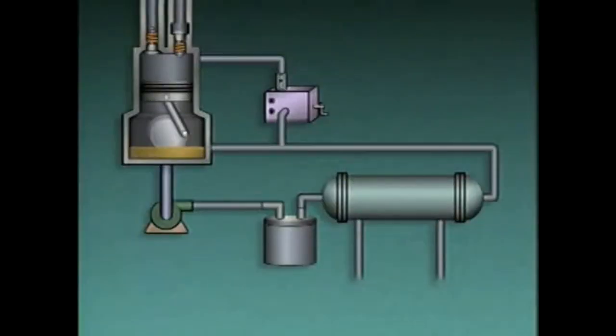Compressed gas systems use auxiliary devices to remove oil or moisture from compressed gas and to prevent overpressurization. Two devices that are used to remove liquids from compressed gas are oil separators and demisters. Most reciprocating compressors that contain pistons use oil to lubricate the piston rings. During compression, some of the oil can become mixed in with the gas. This oil must be removed from the gas to prevent system equipment from being damaged. Oil removal is accomplished using oil separators.